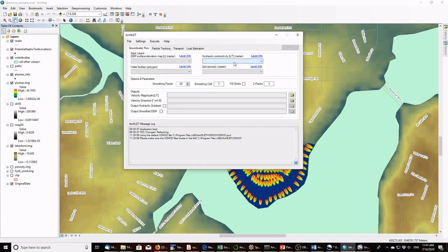One place is hydraulic conductivity, right? So you have the unit of length for the DEM, and then you use this unit for everything of length unit. We have a part 13 that talks in detail about how to make sure the units are consistent, but here I just talk about where you should pay attention to the time unit. So here, the unit of hydraulic conductivity involves time because the unit is length per time, right? So here you would say per day.